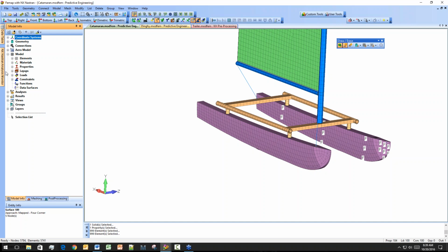The next thing that we'll look at, which is admittedly not a hard and fast analysis function, but it's really useful, is the property icons. I'm sure you've noticed if you've been using 11.3 for any amount of time that now you've got new property icons, and the property icons correspond to what the property type is. And so you can see these holes are laminate element or laminate properties. And so we've got the little plate symbol with a laminate symbol next to it to denote that this is a laminate. The sail, rigging plate, and frame are made up of plate elements, so those have those little plate symbols.